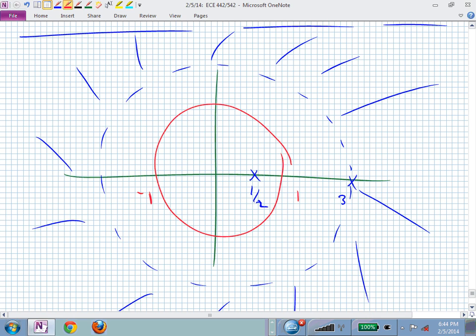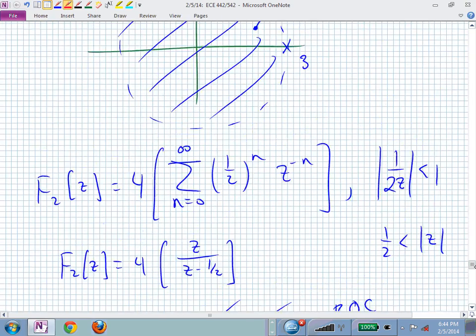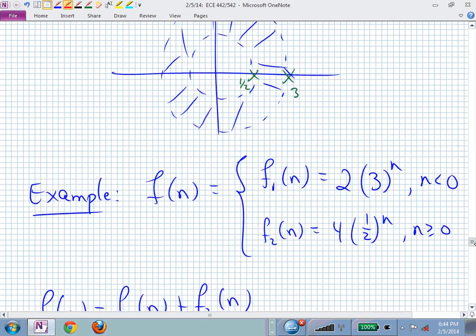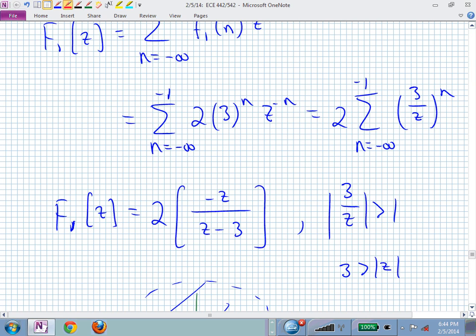So does that mean that you can't just look at the poles anymore and say what the value? That's correct. The question is, you can't just look at the poles of this transfer function and claim stability or not, unless somebody prefaces your discussion and says, we're always going to work with causal waveforms. If they tell you that, then you know that the region of convergence is exterior to the poles. If they give you that additional piece of information, if they say all of your waveforms are causal, they're giving you a big hint.